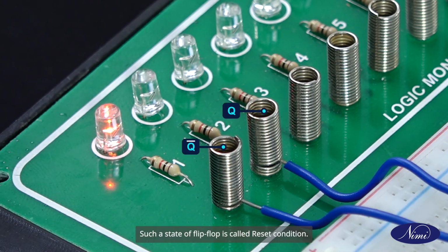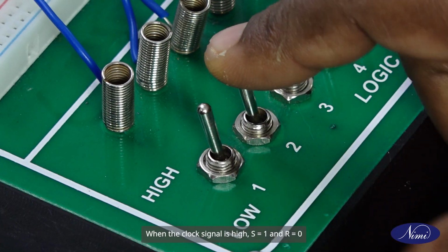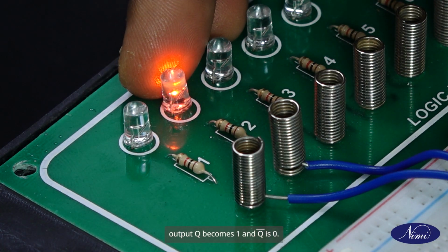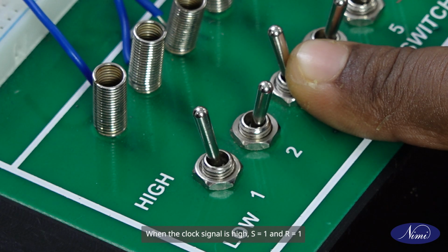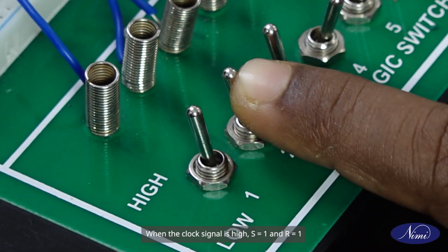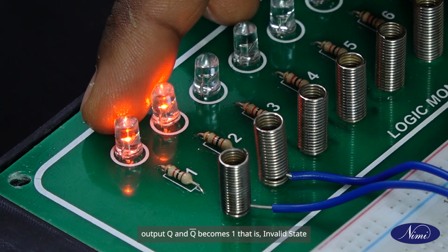Such a state of flip-flop is called reset condition. When the clock signal is high, S is equal to 1 and R is equal to 0, output Q becomes 1 and Q bar is 0. Such a state of flip-flop is called set condition. When the clock signal is high, S is equal to 1 and R is equal to 1, output Q and Q bar becomes 1, that is invalid state.